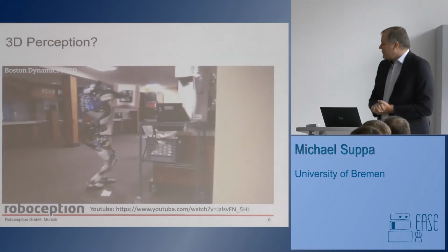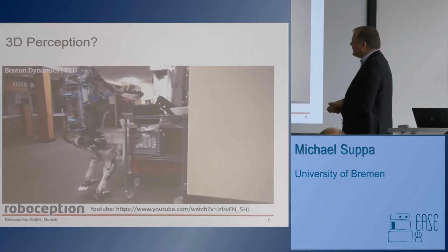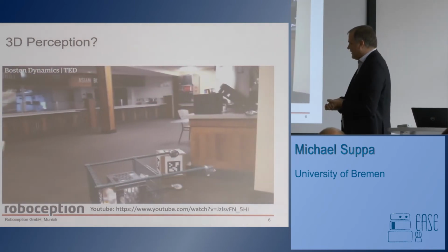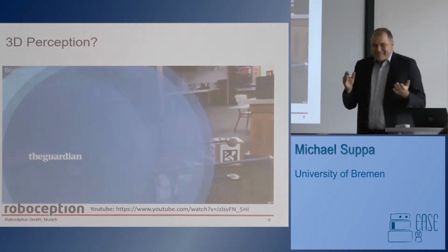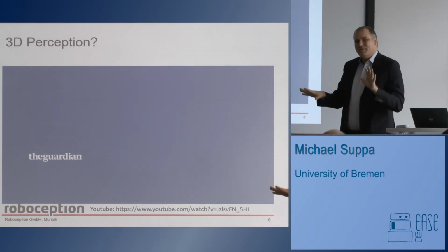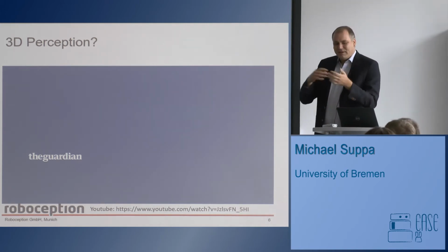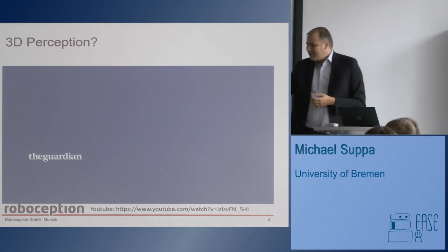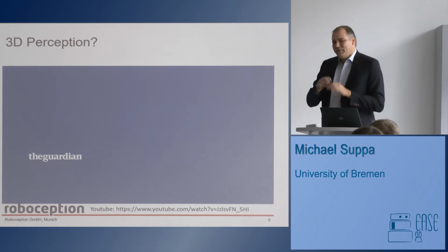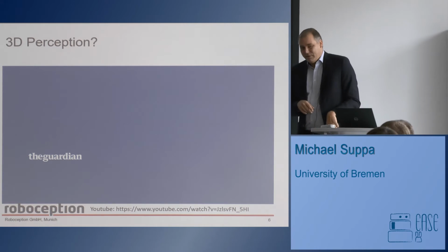Just an example for 3D perception. I like this video very much because it shows you have tags, you have a good environment, and then there are little deviations, and the whole thing just totally messes up. That is basically what happens if you expect everything to be correct, but somehow your model is not. You detect some inaccuracy in one of the markers, you slightly hit something you don't notice. So that's a perfect example of what can happen if you don't adapt to small changes in the environment, and if you're not considering error in your system.